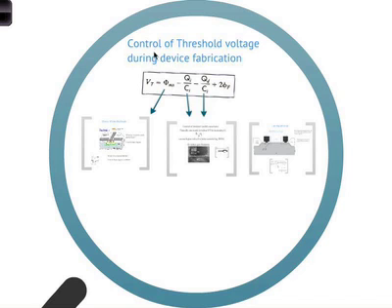If we look at the expression for the threshold voltage, we saw this before. We have 4 terms here. The first term is essentially the difference between the work functions of the metal and the semiconductor, phi ms. Work function of the metal minus work function of the semiconductor. That causes some bending of the bands, to match the Fermi levels, if you remember. Then you have a few terms here.